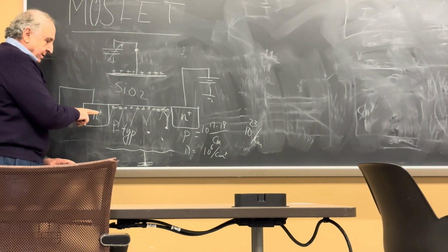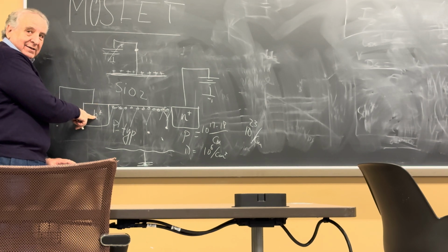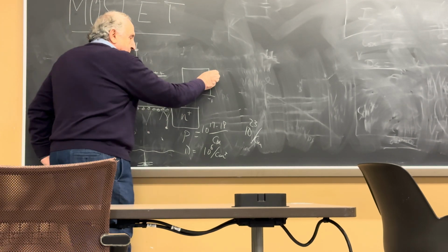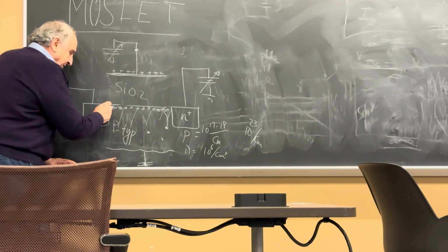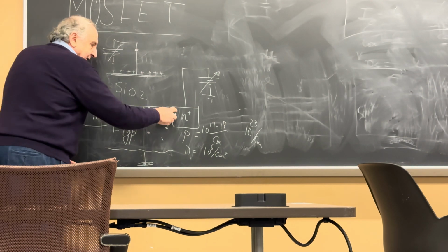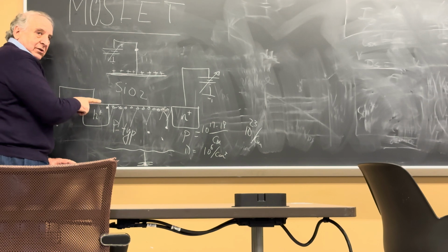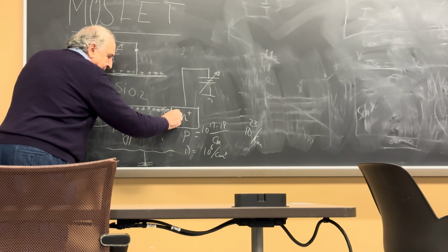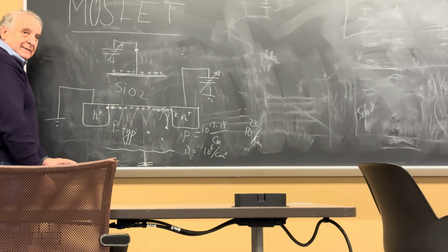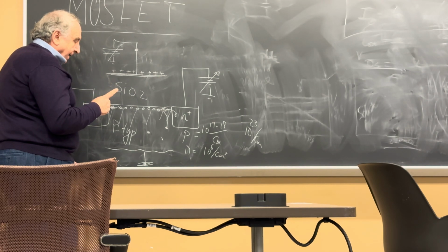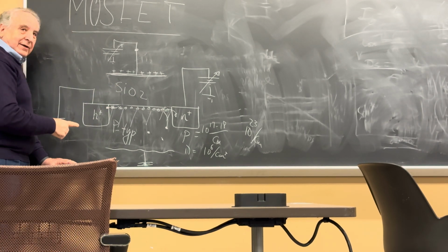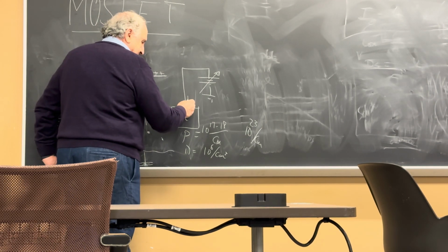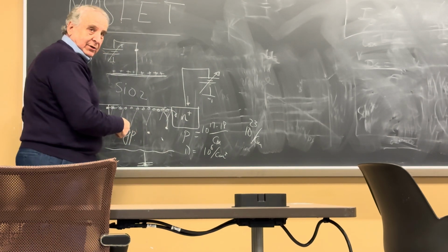Essentially, what do you have? Conductor. A highway between this bucket and that bucket. Now they're making a connection. Now, as you crank this up, what happens? This electron, and this is positive, sees a potential, the field, so the electron goes, right? Yes. All right, now, which way is the direction of this current? Drain to source, right? It's the opposite direction of the electrons.